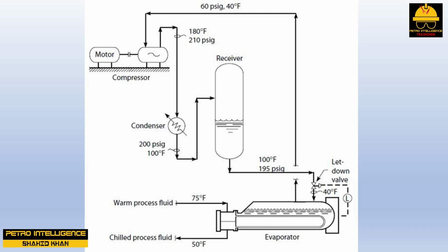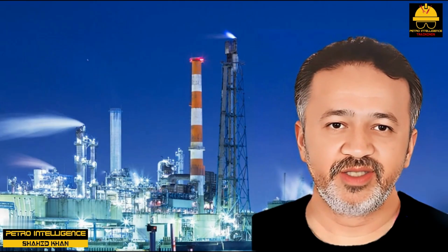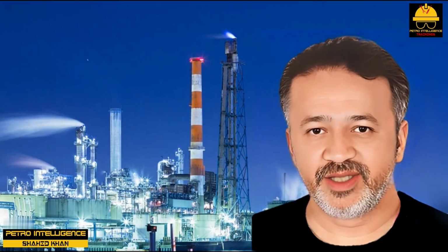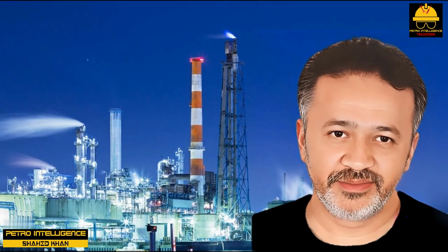For example, adding lighter propane to heavier isobutane in a refinery alkylation unit is a common practice to increase refrigerant circulation. But this will work only when the compressor's driver has spare capacity. Of course, in process operations, there are no free lunches. Spiking propane into isobutane also makes the lighter refrigerant more difficult to condense.